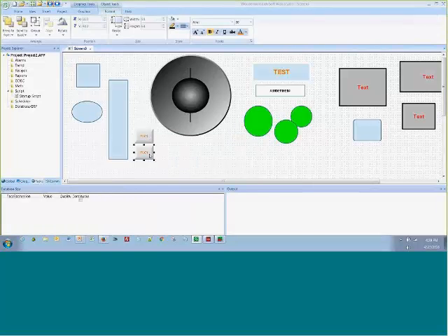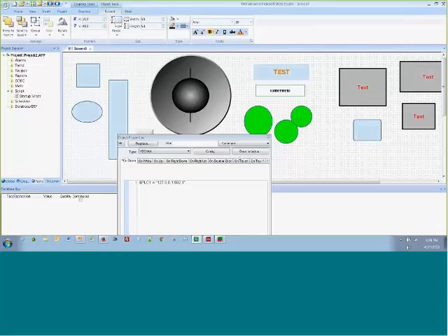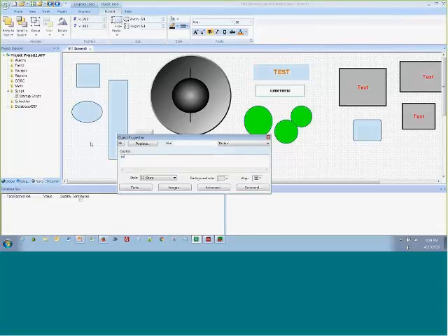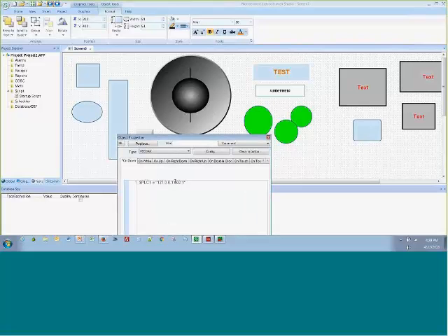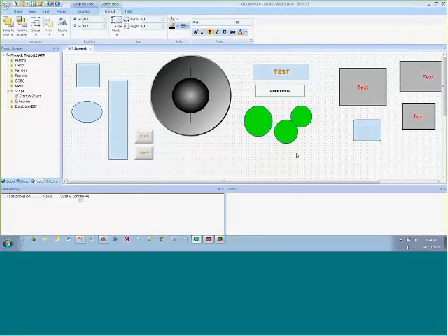And then maybe this is now a different conveyor or a different PLC. Maybe this is conveyor 1, I don't know. We'll give them different names. But then instead of going to 127, maybe we go to 192.168.1.200, which is a PLC that doesn't exist.